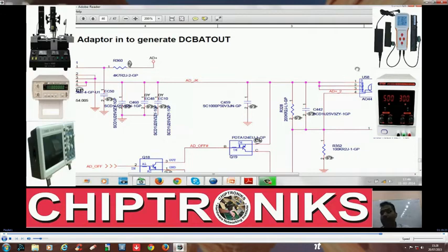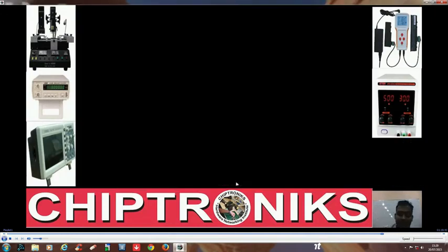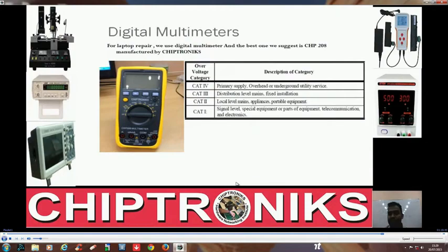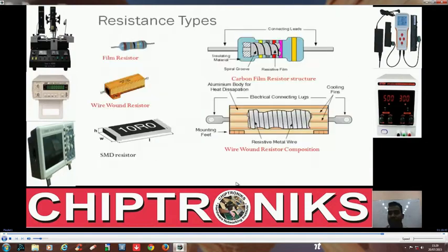You got it? In a P channel MOSFET, the current will move from source to drain only when VGS is negative. At this source, here is 18 volt, the gate is ground, so V gate is less than V source, so it will allow the flow of current. Alright, you got me? If there is any confusion in this one, we have to revise it once again.